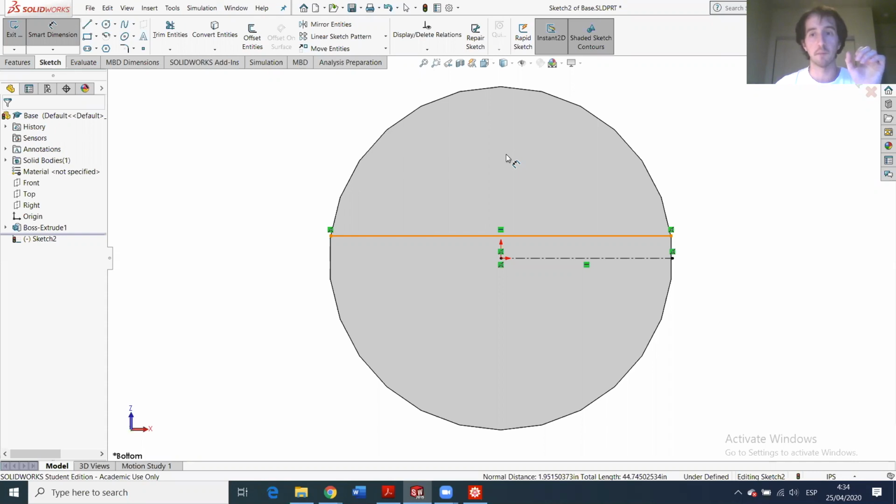Then we will also need to take into account the thickness of the bushings. I have done this design previously, so I can tell you that we will need 6 bushings between here and here. You can believe me, or try it yourself, and when you see that you need more space, just redesign it.